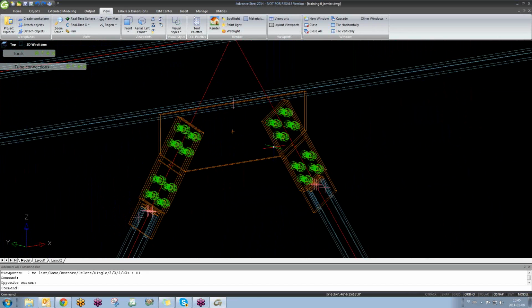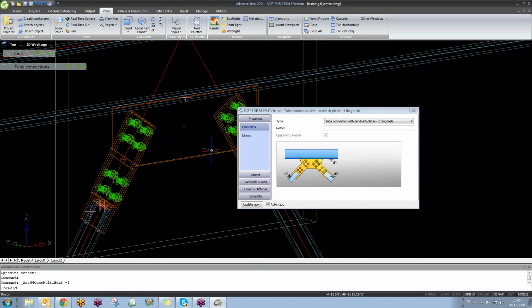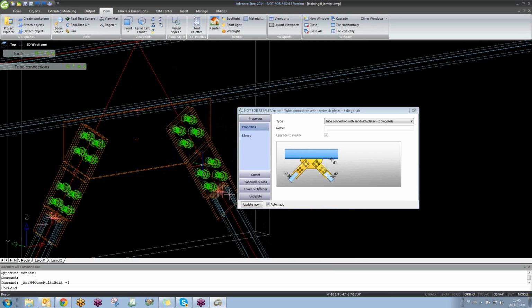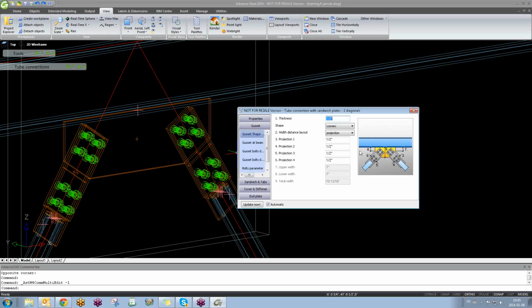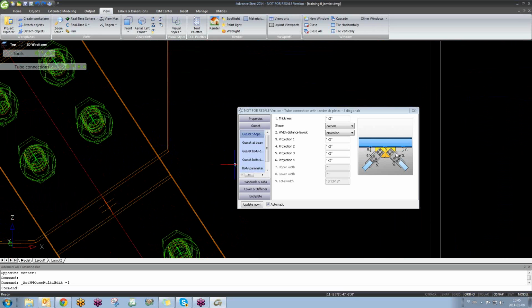The reason why I said that is because when I'm creating connections and I'm looking at my offsets, I'm looking at a different layout of the plates and everything inside of that joint. I can see everything and I know it's where I want it to be. I just got to rotate my screen to see what, like when we were changing the bolts. Well, you don't really need that because, for example, you are absolutely sure about the value that you will need. For example, if you are working here, the number 8, or let's say the number 3, the offset from here, you don't need to rotate your screen to know that it's this one. You already see it here.